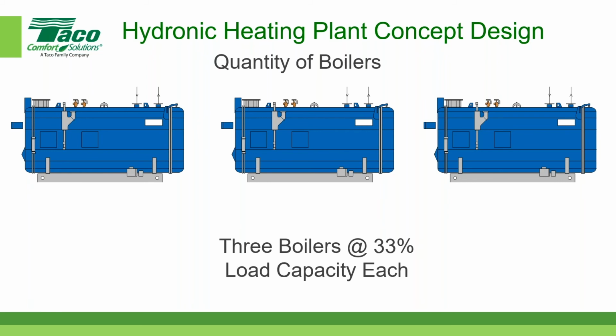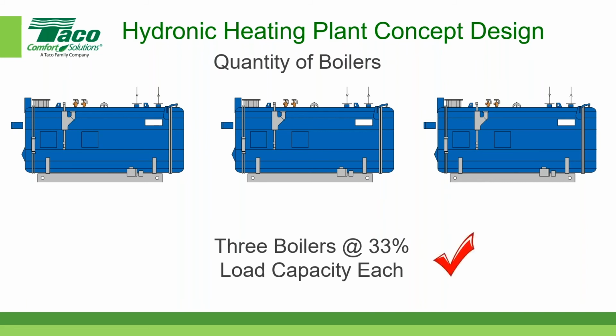or 67%. But if you recall what I said a moment ago, especially in our discussion of a simple office building, probably 67% would handle the building heating needs for more than 95% of the hours. And the advantage of 3 boilers at 33% is now you can lose any one boiler and you probably have enough capacity to handle the overwhelming majority. The other advantage is you get nice turn down, because now that the boilers are 1/3 capacity, they're relatively small. Okay, so when it comes to my preference, I tend to like 3 boilers at 33% each. So I'm going to put a big check mark next to that guy.